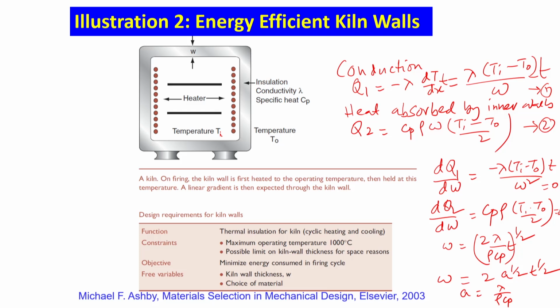So, therefore, simply by minimizing A, I can minimize W. That is my first important aspect of the discussion. Time obviously depends on how much time you can give it for heating. So, this is the first important aspect, and if you want to minimize A, you need to minimize lambda, maximize Cp and maximize rho. So, these are the two important aspects you learn from these small calculations.